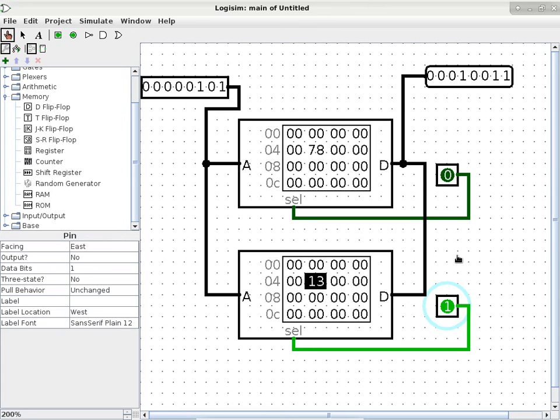What happens when you have a chip that has a different capacity? Well, you can mix chips with different capacity, but whatever is driving the mechanism has to understand that part, so that it can calculate which chip has the select pin activated. So you can mix different capacity. It's just that you have to be careful when you calculate which chip should have the select pin activated, or asserted, using the terminology of EE.